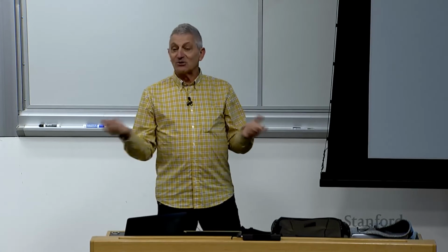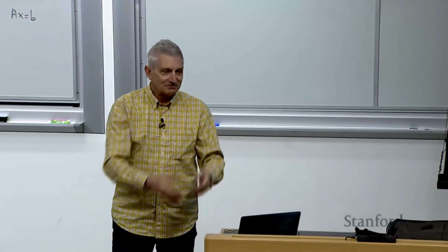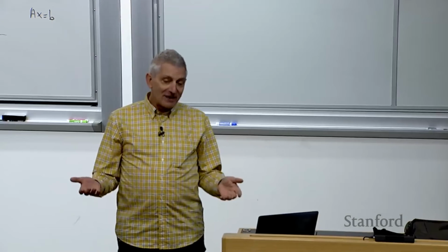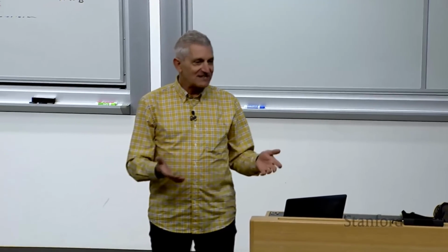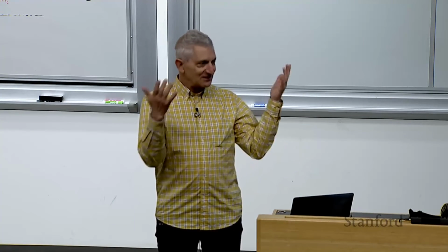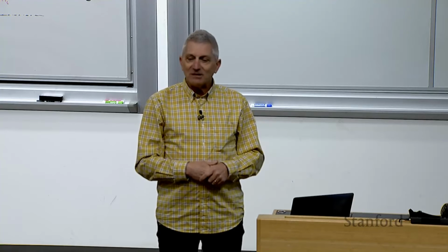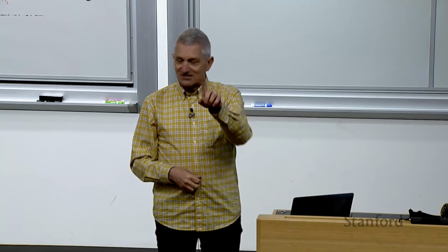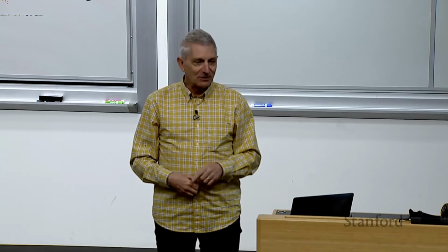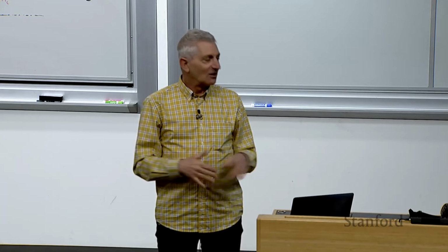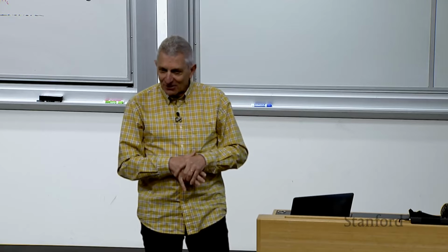Okay. So someone who knows circuits, do you want to guess? I give you a circuit. It doesn't have to be a billion. It's an op amp. I've got, say, 15 transistors in it, or devices. And I'd say, please find me the equilibrium, or bias. That's dialect: bias for the equilibrium point. Everybody got this? Okay. Can someone guess a homotopy parameter?